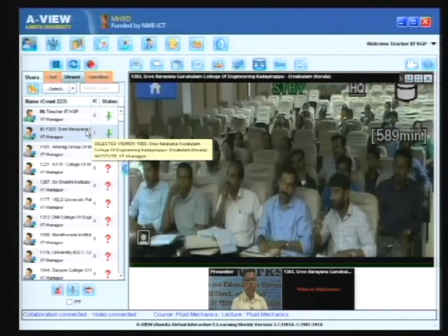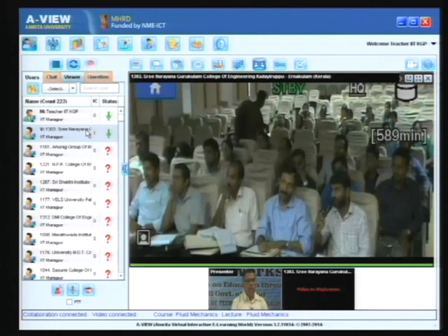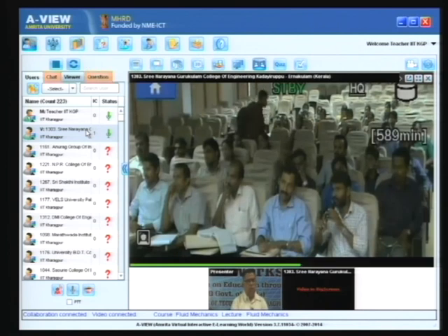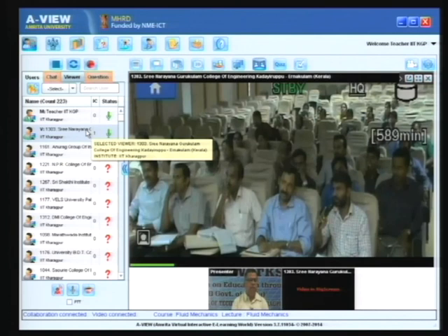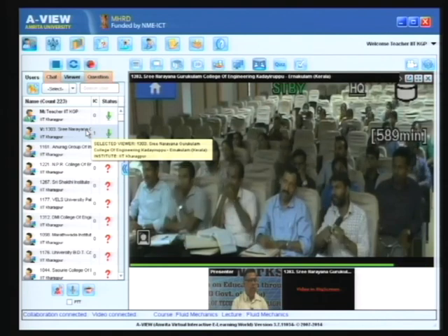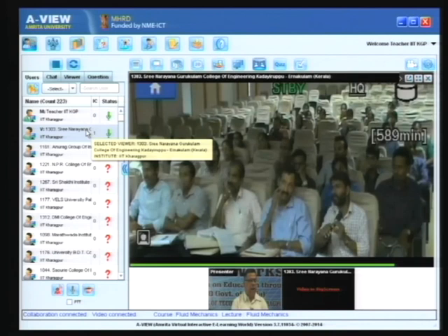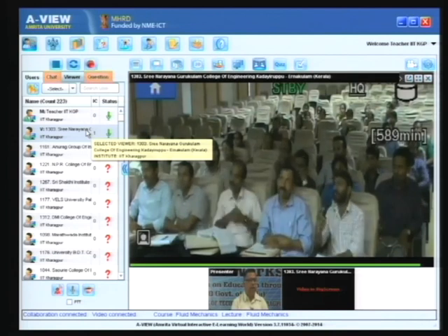That C came when you integrated the differential equation. Mathematically we can understand, but does it have any physical meaning? See, you can find the constant C by applying the boundary condition that the pressure at the free surface is atmospheric pressure. I skipped that part because even without discussing that, I was able to derive the result. Due to lack of time, I did not bother to find out the C. You can find the C by setting P equal to P atmosphere at the free surface.